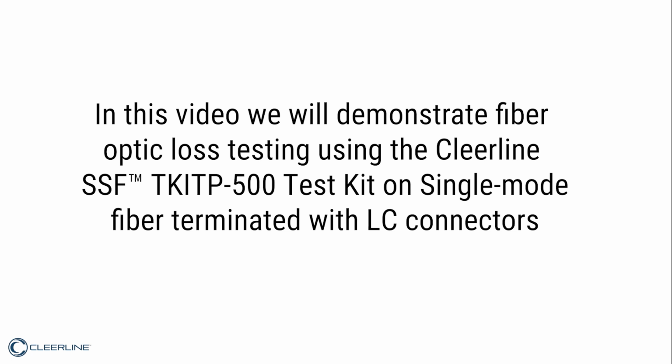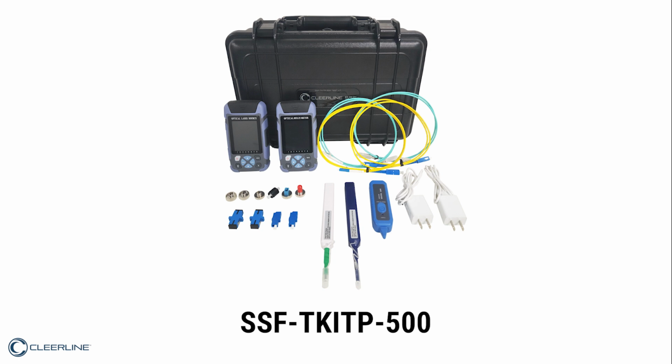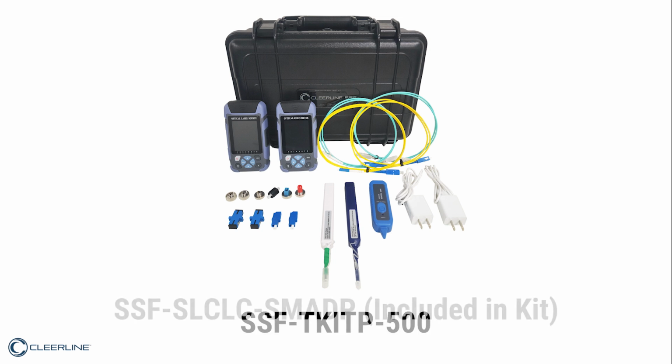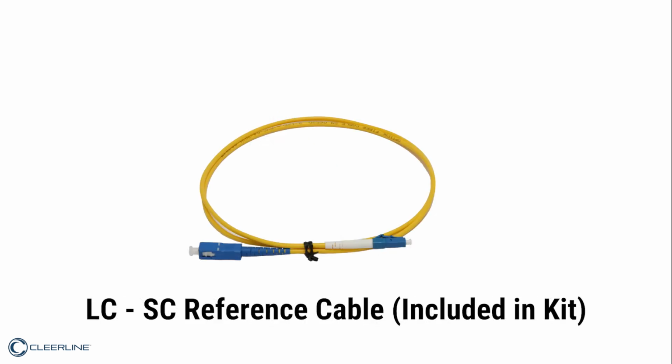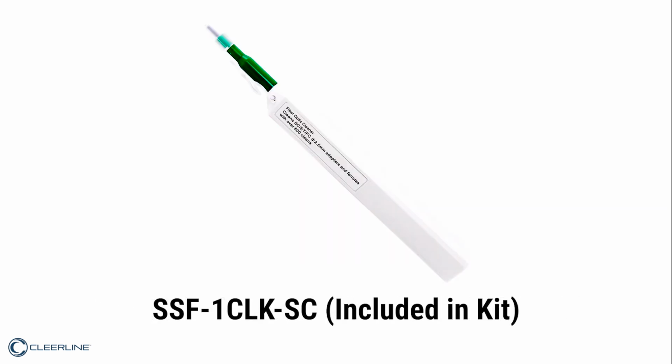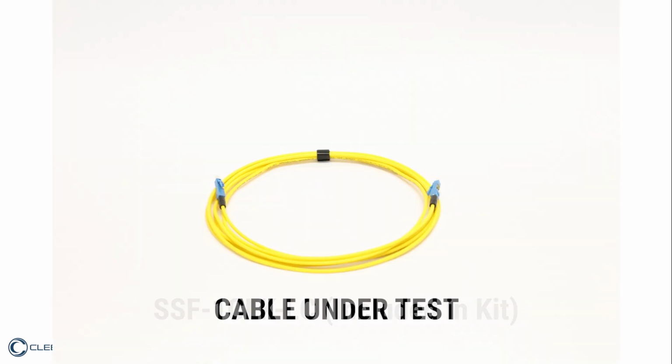Required equipment and materials for test: SSF-TKITP-500 with included reference cables, adapters, and cleaning supplies, LC to LC feed-through adapter, LC to SC reference cable, SC one-click cleaning tool, LC one-click cleaning tool, and cable under test.